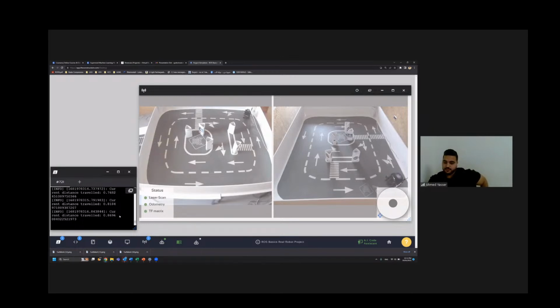Let's see how it solves it. Is it getting lost? Is it going to recover? The controller that keeps the distance from the wall hasn't really done anything that keeps it on a straight line. So you can see that it oscillates, but it would never lose the wall. You could keep this running. It's never going to lose the wall. It's just going to oscillate, but it will always follow it.